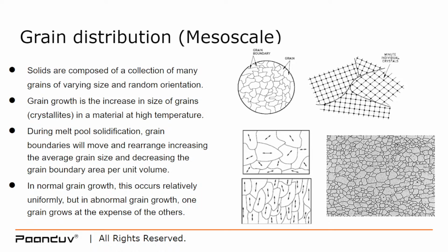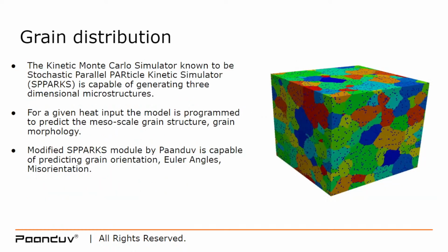Now, if you add heat and then remove the heat from these solids, this grain structure changes and the boundary of the grain changes. The grains can grow or shrink in size, they can orient in a different direction, and this directly affects the quality of the part in terms of its strength, fatigue, and creep. In the images you can see that there are different orientations for the grains, and in some of the upcoming videos I will show you how the orientation and the size of these grains changes if we run a laser over them, which is typically the case in 3D printing processes.